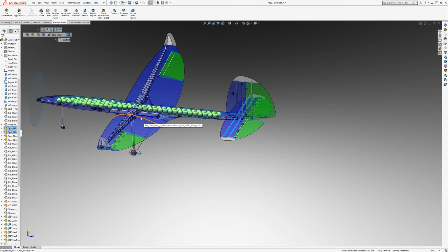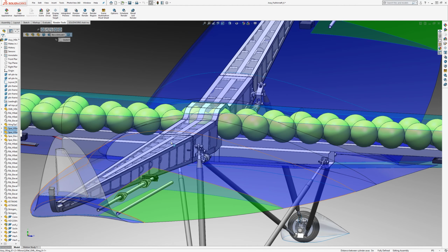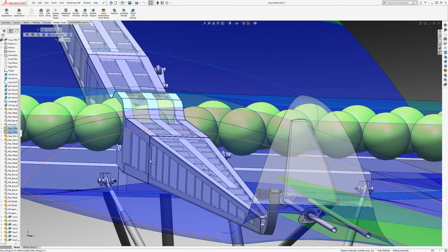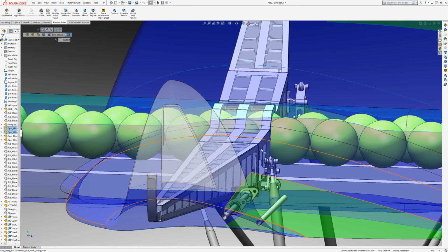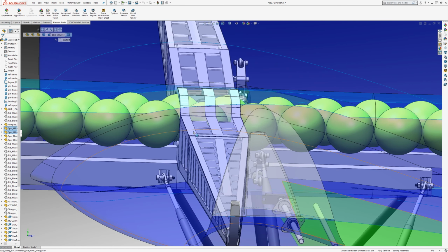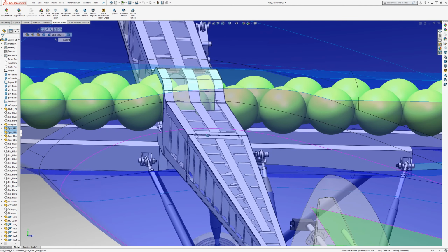And the other way that it could be transferred is, let's say in this case with this wing box, here we have the spars. The front and aft spars can each transfer a shear, like an upwards or downwards force. But also there are horizontal forces that can be transferred from the skins. There are shears in the plane of the top skin and the bottom skin, and the overall wing box can transfer a torsion from the wing.